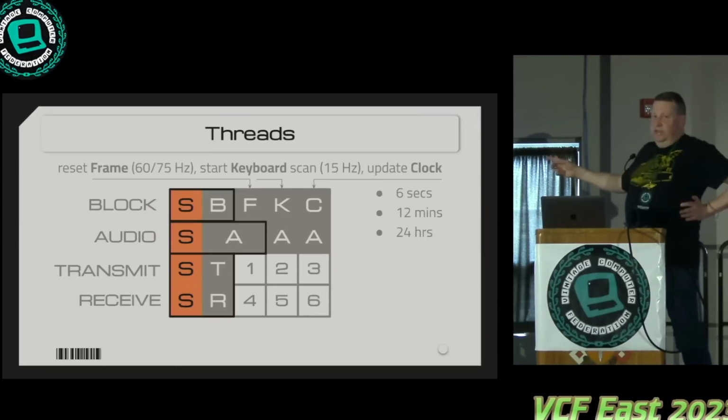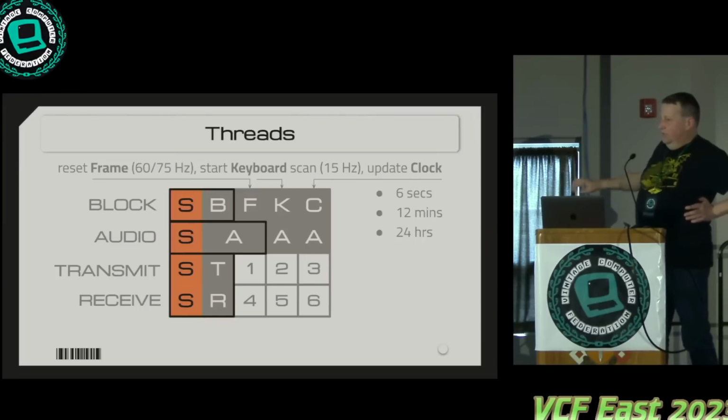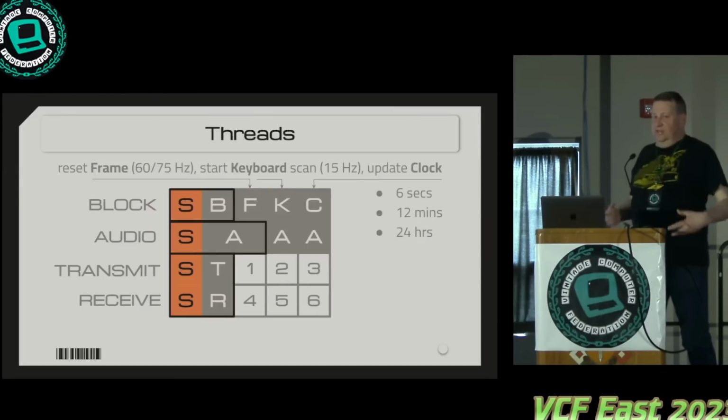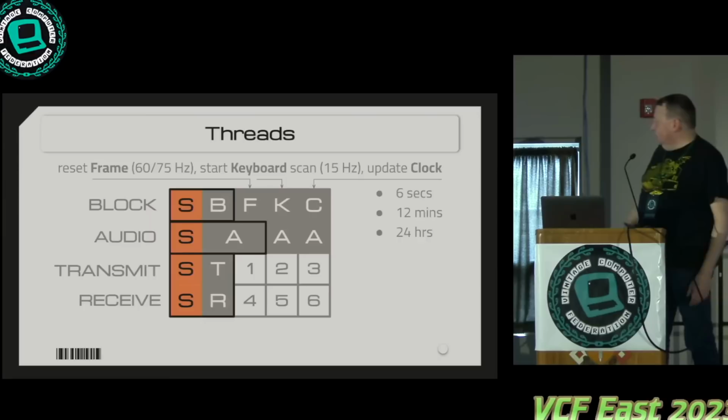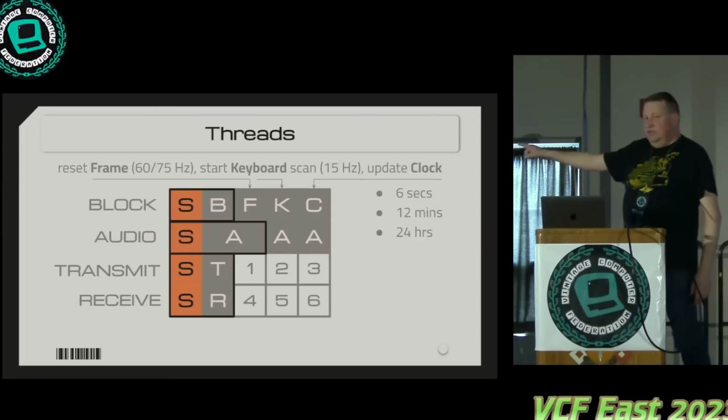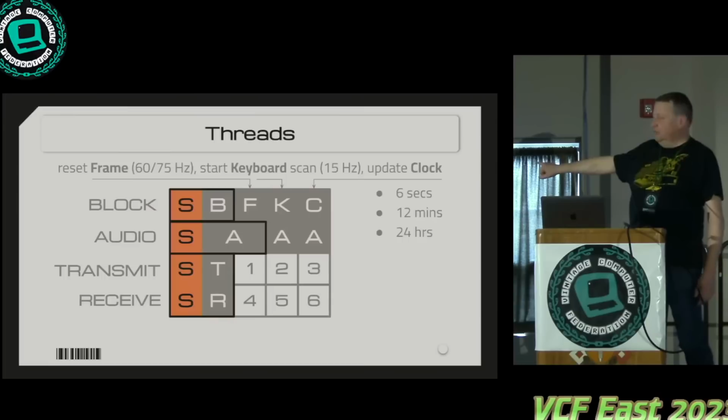And there's also a real-time clock. So this can go up and consume all of those cycles every 6 seconds, and it updates these counts to keep track of time. There's basically 3 timers. The audio is very labor-intensive because it's all doing math to calculate the waveform. So if you turn on the audio, it uses up 2 cycles immediately, and you can add up to basically three voices of audio. So with all 3 turned on, it takes all 4 of those cycles.